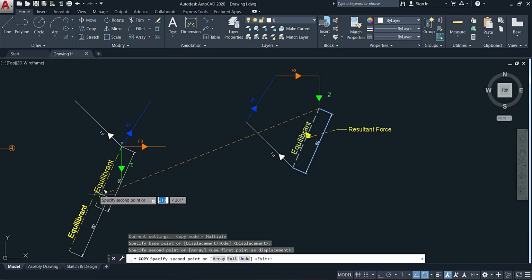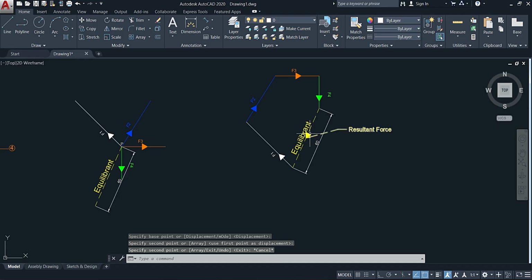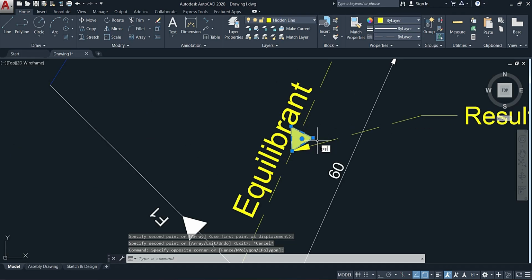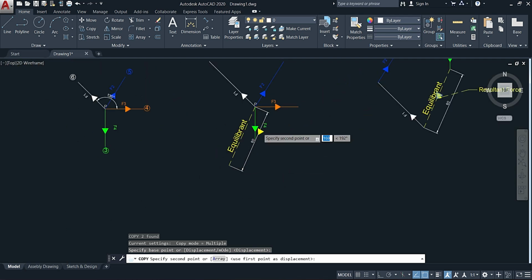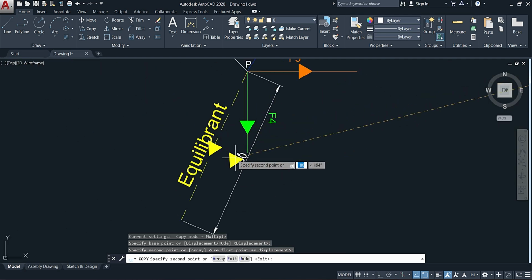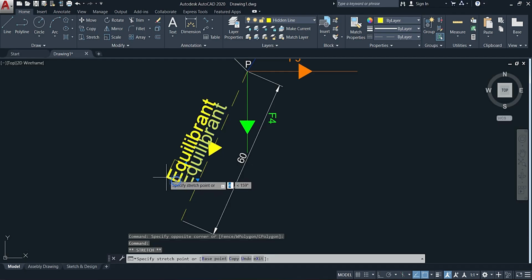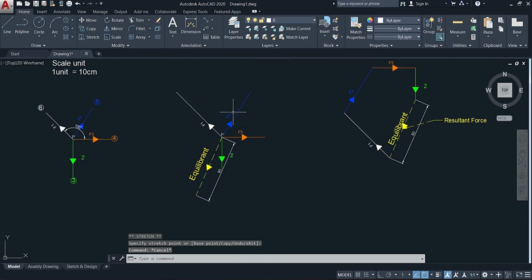So this force, when placed on our force diagram, this equilibrant here, we now know that the force is acting in this direction that basically cancels out all of these here. So this is the resultant force if you want to think about it like that. All right, so this is now our fifth force, and this fifth force measures 6 units.